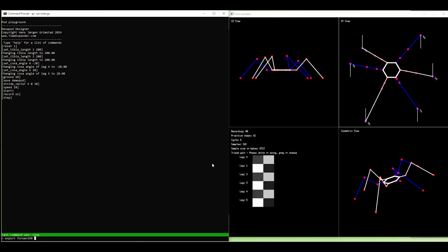Next is the maximum range of the servos. Some servos may only be able to rotate maybe 180 degrees. Others maybe 300, so I'll specify the maximum rotation angle of the servo. In this case it's 300 degrees. Next up is a bit mask that indicates if you have flipped the servo upside down. The servo horn should always be pointing in the positive Z direction of the local reference frame. If it's inverted, like in this case, I'll specify a 1 for inverted coxa, not inverted femur, and not inverted tibia.